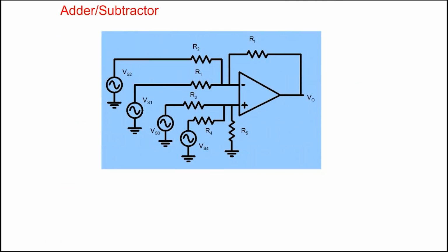All right, so in these cases, it looks complicated, but conceptually fairly simple. We have several voltages, Vs1, Vs2, Vs3, Vs4 here. So use the superposition theorem to write down each value here. So due to Vs1, remove all of them. Vs3, Vs4 are all shorted, Vs2 is shorted. You should be able to see that the only thing that matters is R1 and RF here.